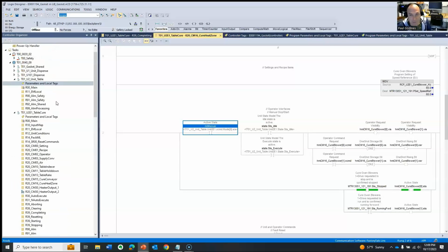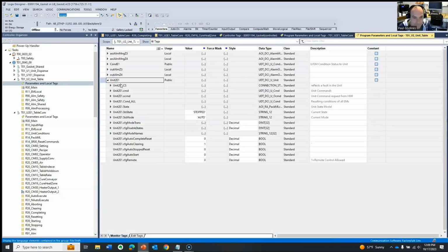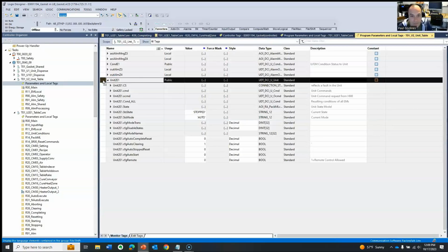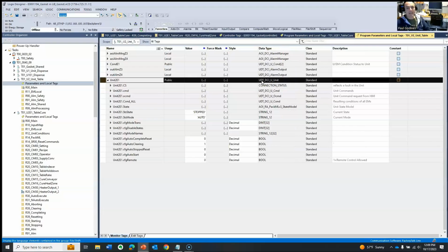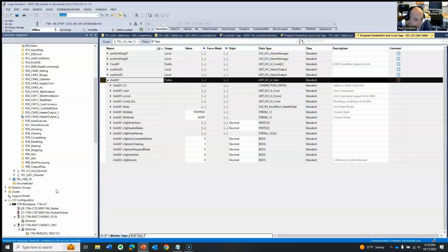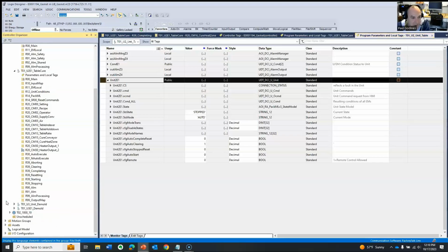Now, OCMD, all right, what are we talking about? Well, let's go back to our tag, right? Our unit. When we look at our data type, we see that it is what? A UDT, right? For those of you who are unfamiliar with UDTs, I'm going to make comprehending them extremely simple. This is the way I look at them. A UDT is a filing cabinet. It's where I'm keeping a whole bunch of my tags that are associated with a specific function or device.